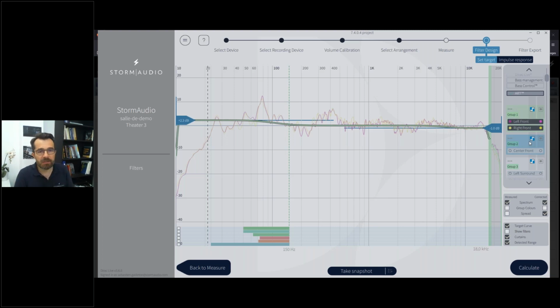One of the recommendations we can make is that if your center channel is not highly capable in terms of SPL, you might not want to use it as a support in the system, because the dialogue, the center channel, is where you have maybe 70% of the use in home cinema. So it already gets a lot of energy from just the content. By loading it with more, by using it in art, might not be relevant. That really depends on your center channel capability. So you can leave it alone or put it together.